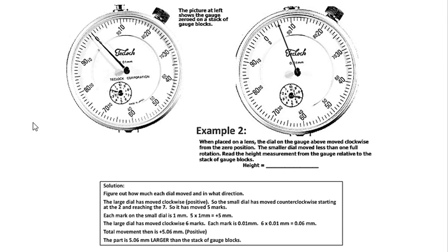Take your gauge block, measure it, count revolutions, swap it, get the object, measure that, add or subtract from the gauge stack, okay. So this is the way you should be going instead of writing this way, because this one doesn't really tell you where the gauge block is. Are you measuring the gauge block, or are you measuring the part, in this way of writing?